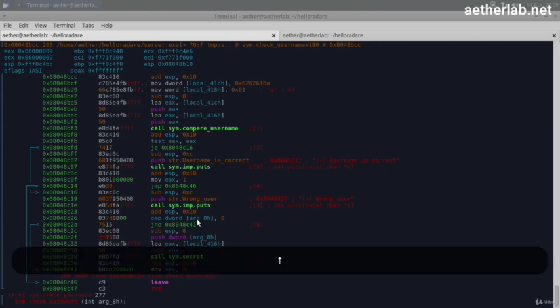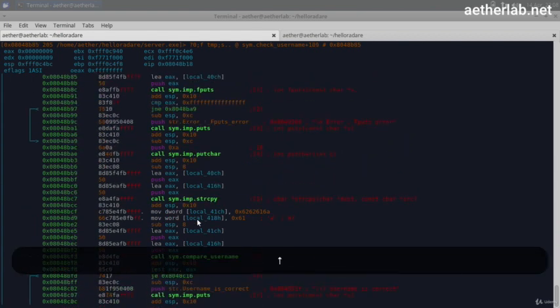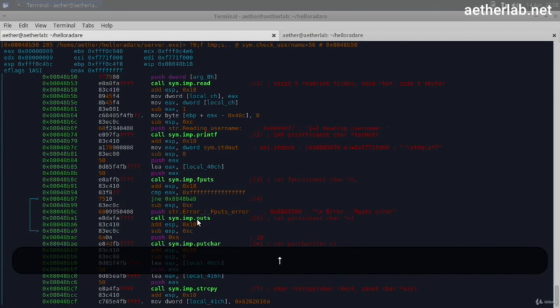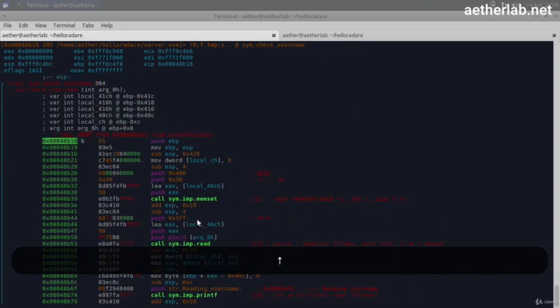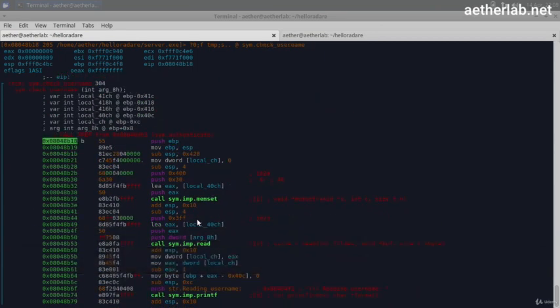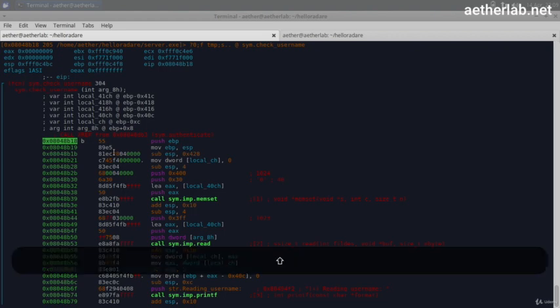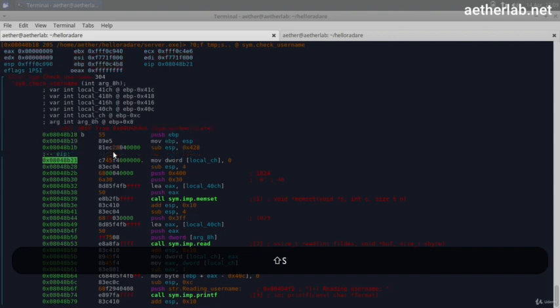What we're going to do is just step over all instruction calls until that point and then see what's happening there. The step over, that was capital S. Oh, by the way, you see this shows that we have a breakpoint here, just for your information. So with capital S, we start executing the instructions. You could see on the top how the registers are changing.